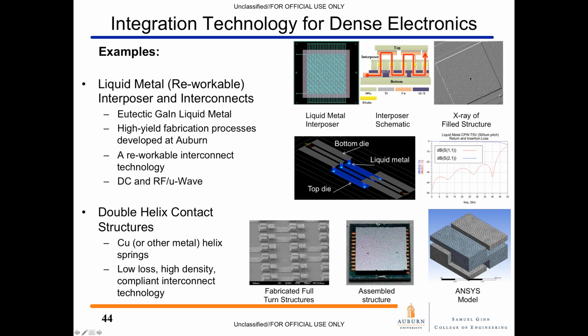Now you can see the X-ray here. We get nice, good filling of this. And so this is an active area of our research. We're looking at the DC and RF performance of this. And the idea would be that you could plug and unplug this top chip from a reworkable perspective.